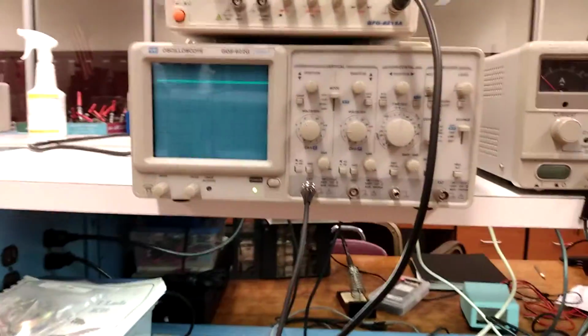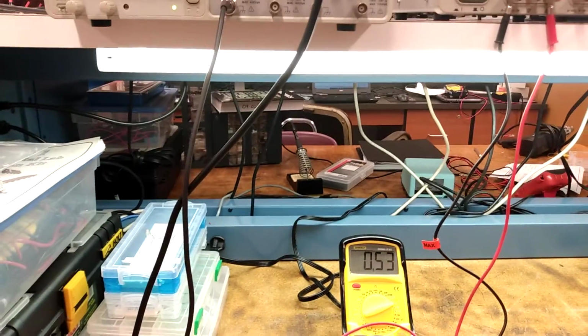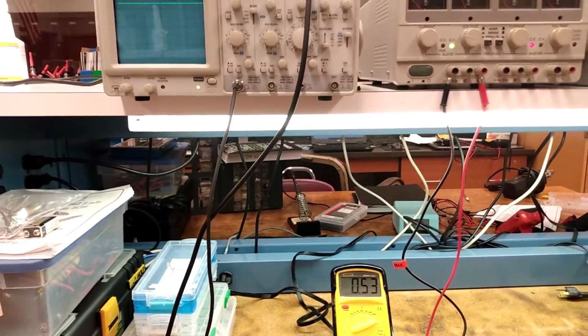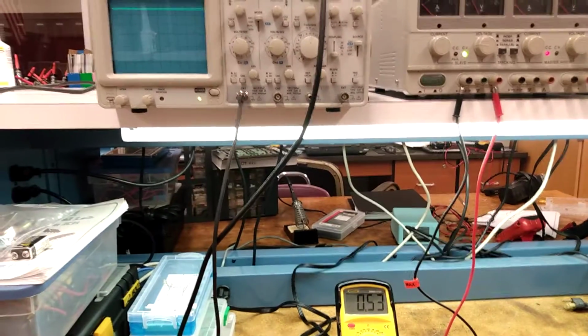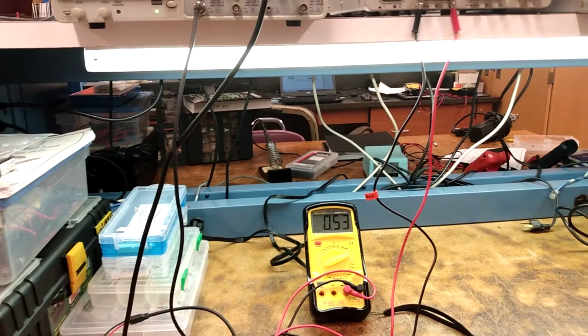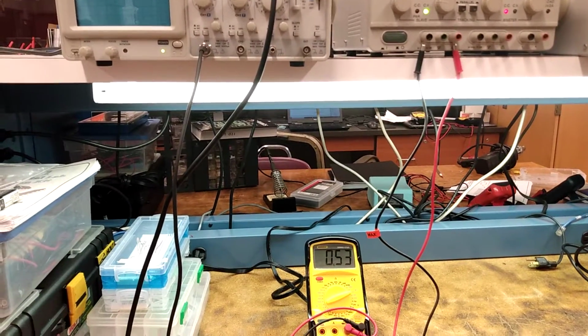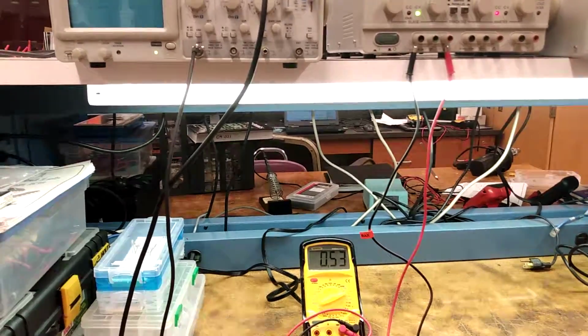Our oscilloscope showed us that as a straight line, and our digital multimeter also proved Kirchhoff's law. So the series portion of this circuit showed us that a DC signal on an oscilloscope is a straight line, and we were also able to evaluate Kirchhoff's voltage law. Let's reconfigure this for our AC source. I'll be back to you in a minute.